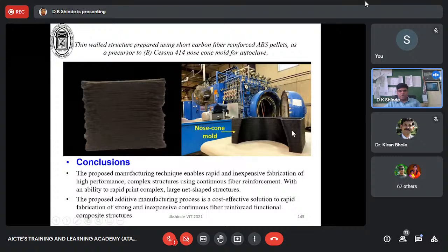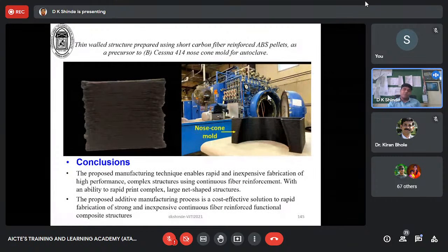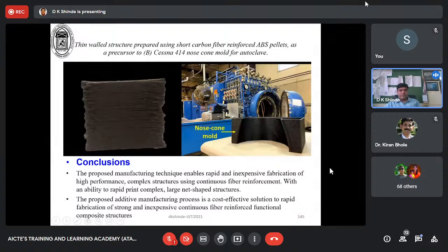In this kind of process, you have big curing ovens for the thermoset resin, maybe autoclave methods. But if you have such an extruder, what you see over here, and these are the controlling elements, you can build such an element over here, or you can create a chamber, and inside the chamber the entire extruder will be moving as a robotic arm, and you can prepare such large 3D printed shapes and sizes of high strength, low cost material with rapid cooling methods, and throughput in a short duration of time.